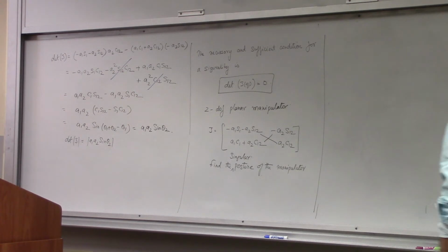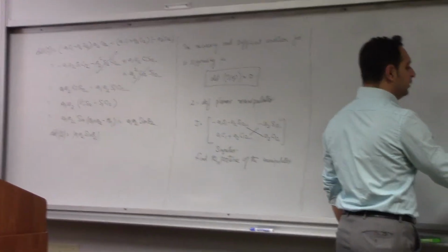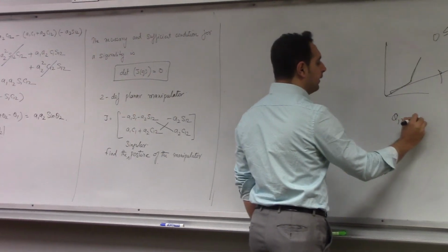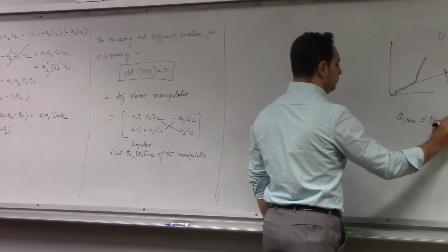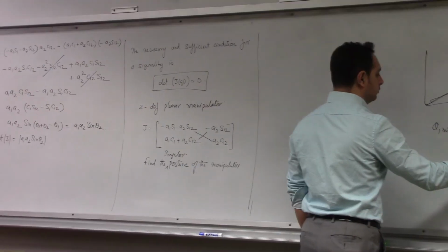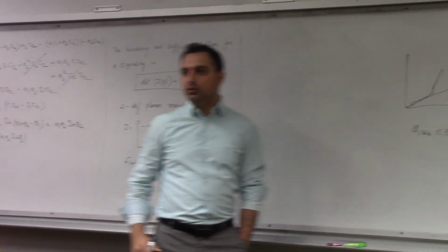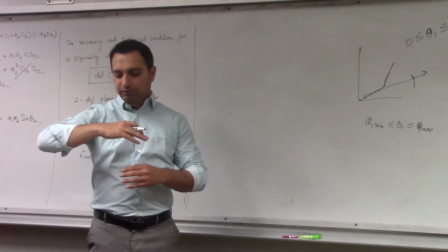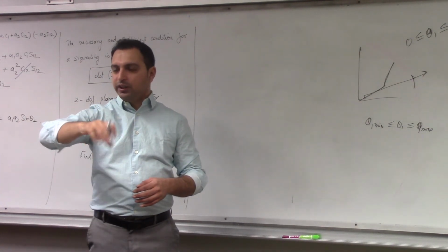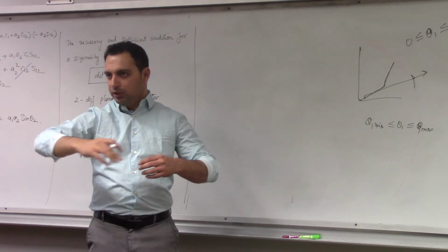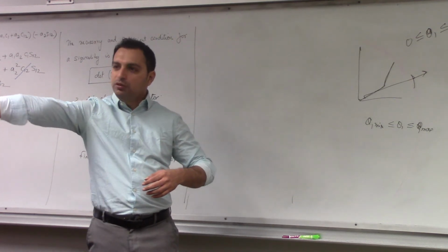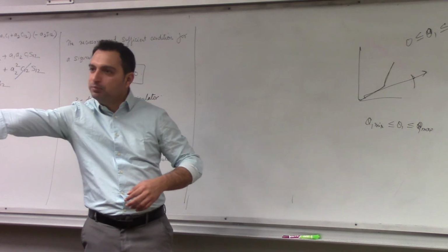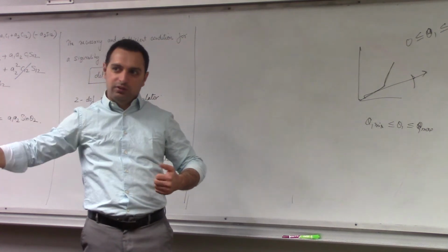Joints are limited, so theta 1 will have a minimum angle and theta 1 maximum. For example, this is a 2-degree of freedom arm. When my arm is here, I'm more dexterous, I can move in any direction closer to my body. If I move forward, I cannot move any further. Even if I want to pick up something that is away, I can't move any further.